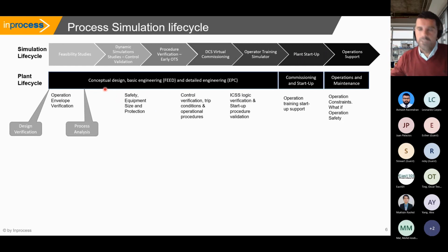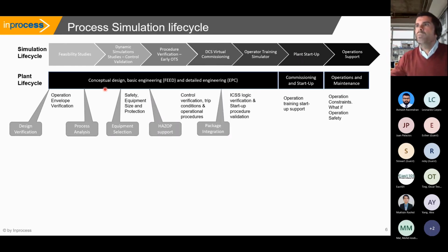The second item that we address with process simulation is the process analysis itself, helping in the equipment selection, supporting the HAZOPs, doing a complete package integration and the analysis not only of the standalone packages like compressors, like GTs, like separators, etc., but the integration of the different packages to complete the topside of an FPSO.